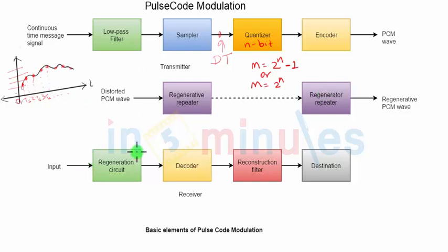Before the signal reaches the final receiver circuit, it may happen that it is greatly attenuated. Now, because the signal which is transmitting is digital in nature, it is possible to regenerate the original levels of the signal. That is because at any given point of time, the signal level will be either corresponding to logic 1 or corresponding to logic 0.